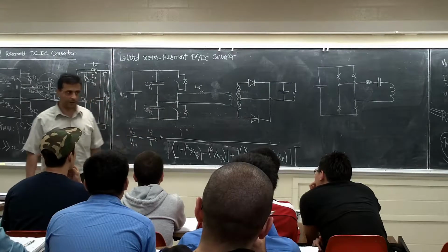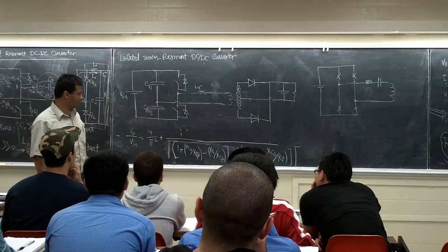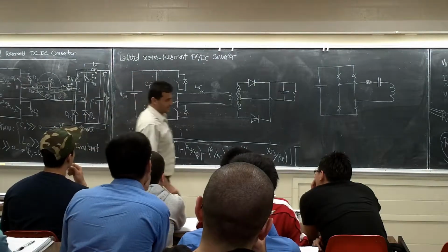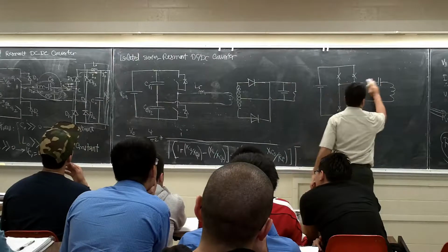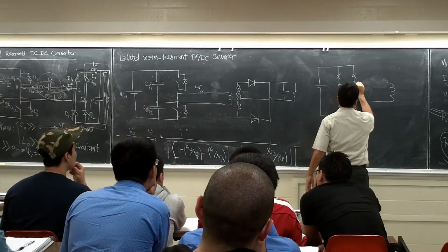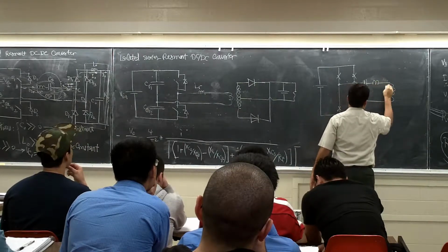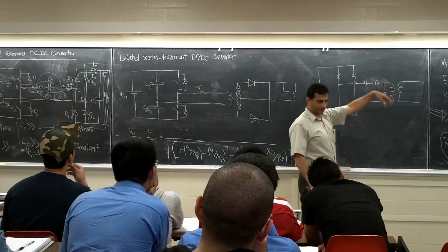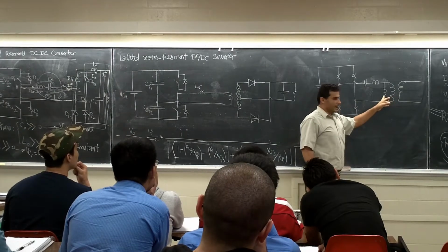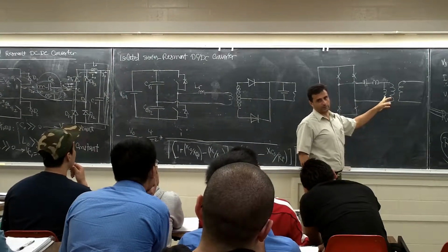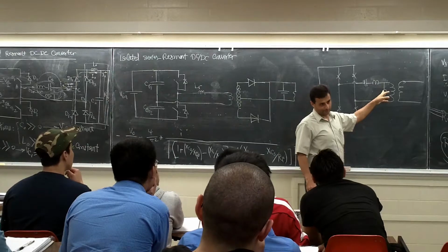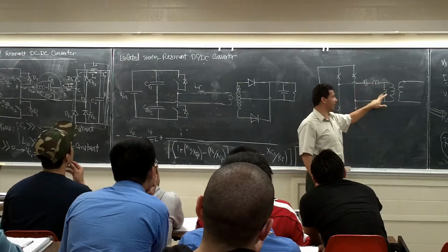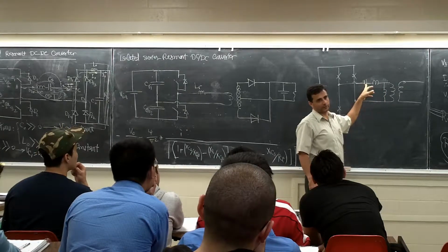Tuesday I'll talk about the Infineon circuit. The Infineon circuit is like this. It could be half bridge, full bridge, whatever here, but it's like this. They call it LLC. I don't care about the rest over there. You remember from the transformers, they have an LM, right? At one end, and I have one L here, and C. They call it LLC. That's a very popular resonant converter.